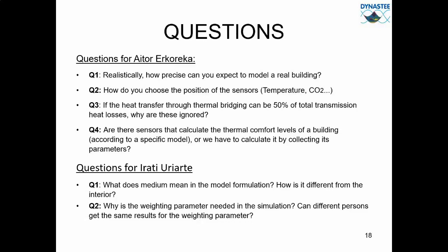Okay, when we simulate a wall, we consider there are hypothetical layers between the interior and the ambient, in order to make the models estimate the parameters these layers could have. So the medium is not a real layer, and we don't have measured data for this point. However, what we can do is make the models estimate the hypothetical temperatures this point could have and check if it's reliable or not, comparing it with the rest of the temperatures and the location of this point.